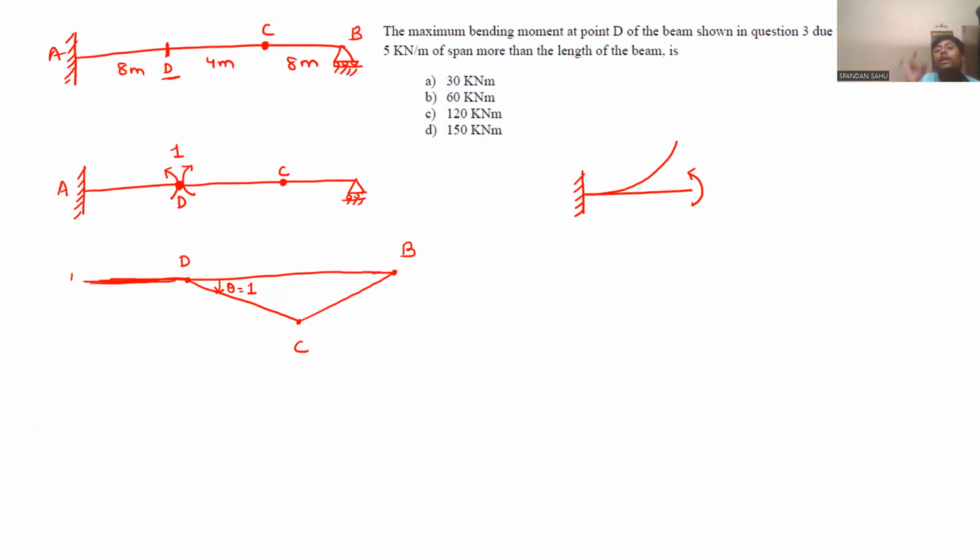It will only take a linear or constant shape. If not linear, then it will be 0 directly. So for the AD section, it was 0 because when you put unit rotation, the AD portion will try to bend non-linearly, and for a statically determinate and linear elastic structure the ILD can't be non-linear. So put directly 0 there.